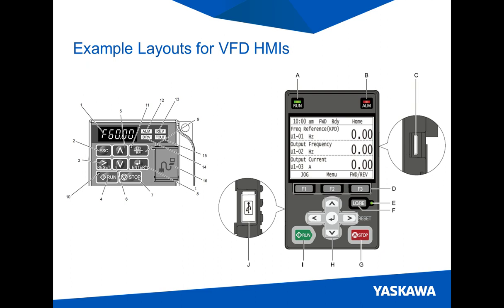Here I'm showing a couple of example layouts for some typical HMIs for VFDs. Some of you in the audience may recognize these in products that are sold today. As you can see from looking at these, the designs can vary quite a bit. Lower cost, small capacity VFDs may have limited featured HMIs with limited displays or fewer buttons. This is actually a result of a fine balance between the VFD features and the intended application for the VFD.